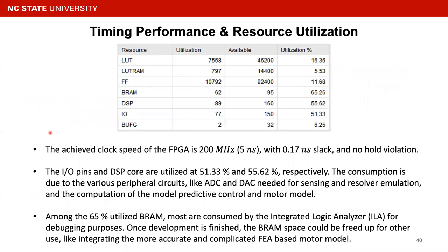So here's the timing performance and the resource utilization. We also achieved the 200 megahertz clock speed for this application, and there's 1.0717 nanoseconds slack, and there's no hold violation. The I/O pins and the DSP cores are utilized at 51 and 55% respectively. The I/O consumption is due to the various peripheral circuits like ADC and DAC needed for sensing and resolver interface.